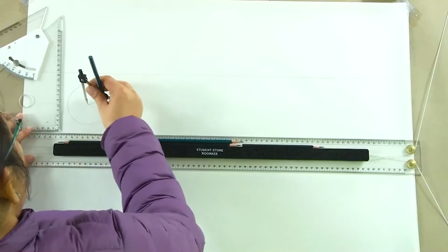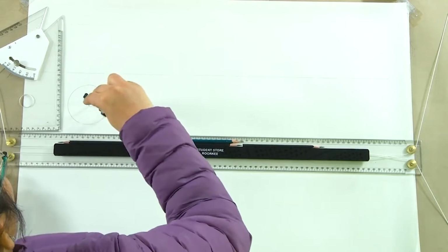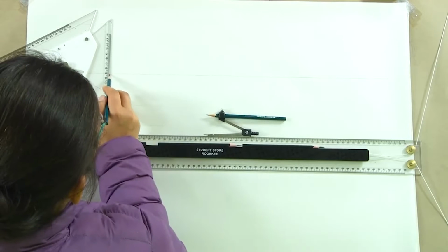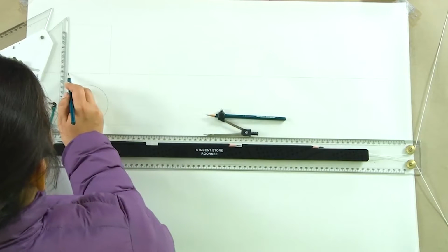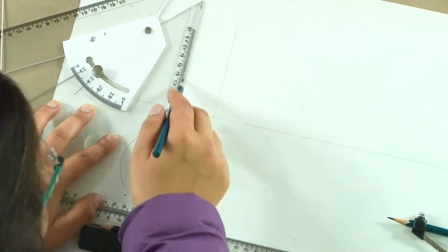So, I am assuming here that we have one upright cylinder of radius 4 centimeter and it is kept in HP. So, this is what I have drawn and we will then take its front view. We are assuming here a height of 10 centimeters for the cylinder and this is where the axis is going to pass through.